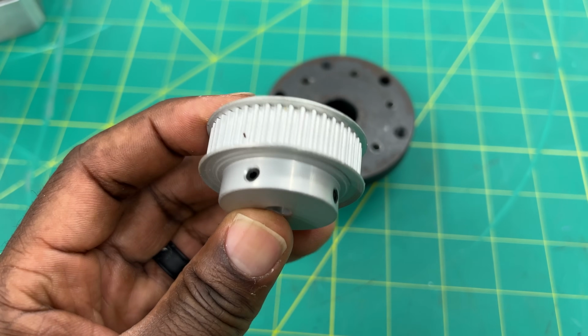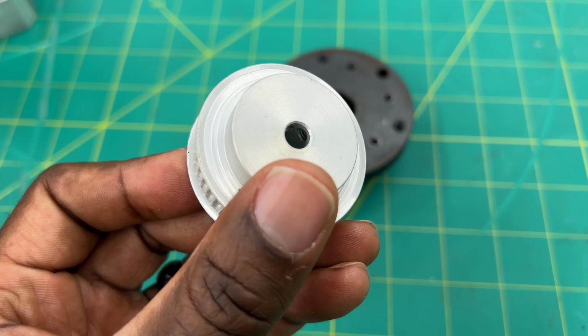Since we're talking about the hub, I want to pause here and talk about just how important this connection is between the shaft and your gear. This joint needs to be able to handle all of the forces coming through it. It's part of your powertrain. And so if the gear can slip on the shaft, you won't be able to transmit the power. There are a whole bunch of different ways to make this connection. It might be a set screw, which is going to be one of the weakest possible connections.